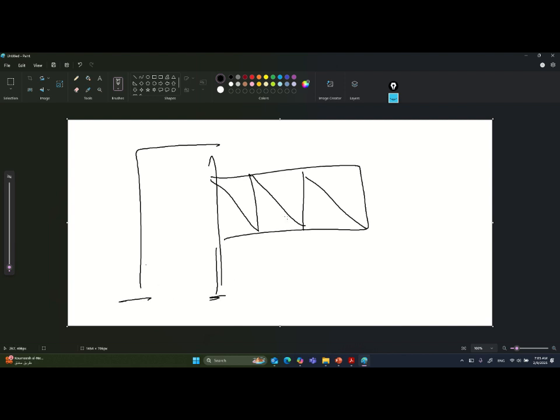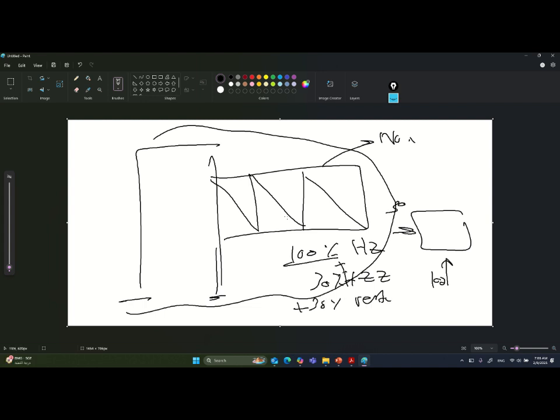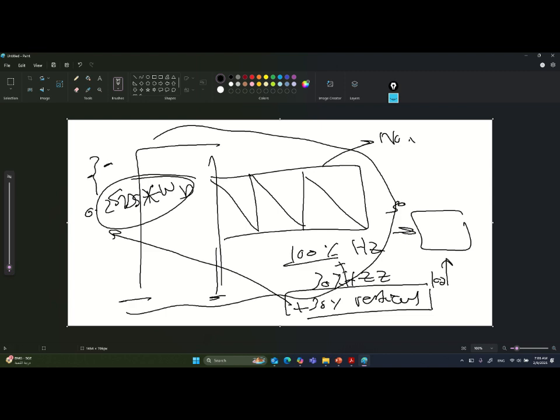So for the component of the hanging structures, however it's related to the non-building structures, similar to or not similar to building, I will use 100% from one horizontal direction plus 30% from the other horizontal direction: 100% here, 30% there, and 30% for the vertical distribution. The 30% of the vertical distribution, which is 0.2 I think, is the SDS multiplied by the weight. So I will consider 30% of this value.